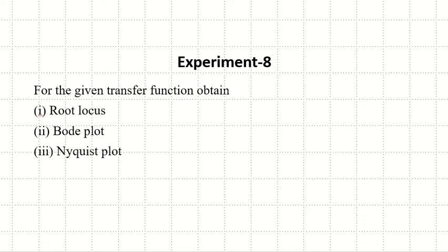Likewise, for plotting the Bode plots, you will be using the command bode, B-O-D-E, and for plotting Nyquist plots, you will be using the command nyquist. So it's very straightforward and simple using MATLAB to plot each of these plots, or the approaches that we have already studied in control dynamic system analysis.